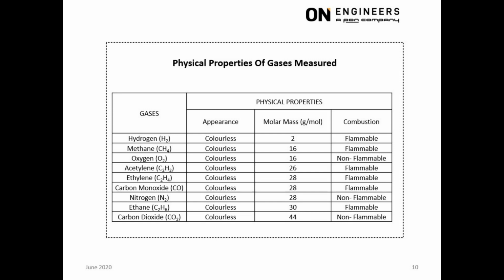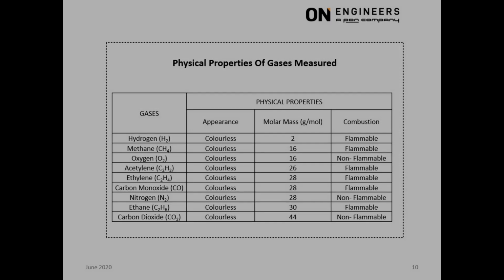The presence of hydrogen will indicate PD. The presence of acetylene will indicate arcing fault. The presence of methane, ethane, and ethylene will indicate thermal faults. The presence of carbon dioxide and carbon monoxide will indicate problems at the paper insulation. Large variation in oxygen and nitrogen will indicate contact of the oil with the outside air.